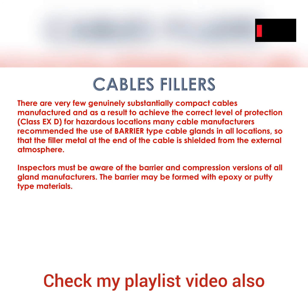The inspector must be aware of the barrier and compression versions of all gland manufacturers. The barrier may be formed with epoxy or putty type materials. That's why you need to understand, if you are involved in the inspections or during the construction, if you are the supervisor engineer, you need to know the different types of cables, different types of cable glands, and how you terminate them. We have a manual to study, so during the time you are working, you become familiar with it.